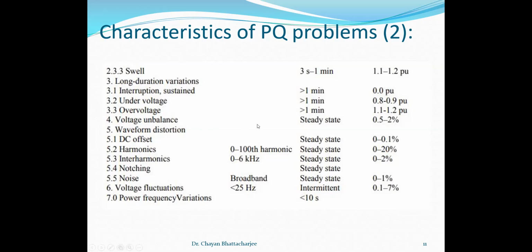If zero sequence currents can flow, as in a YG connection in a transformer, they flow into the ground, and therefore you will not get any zero sequence voltage. But you will only get a zero sequence voltage if the currents cannot flow, say if there is a delta connected winding, or a Y connected winding without any ground. If no ground is provided, then obviously zero sequence currents cannot flow, and you will get a zero sequence voltage.